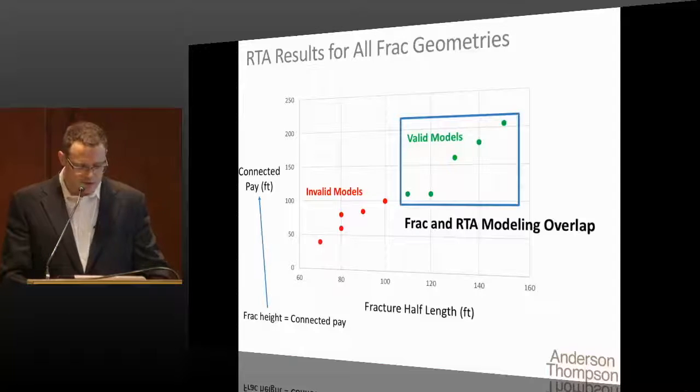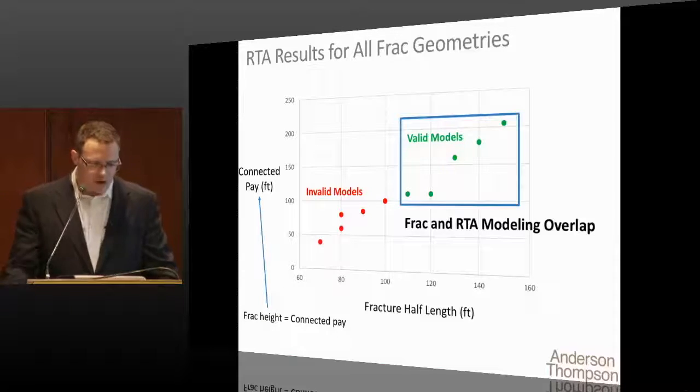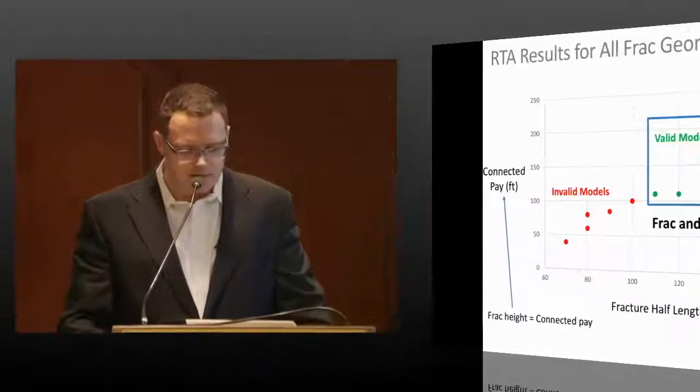Anyway, we're still down to these 5 runs. How do we hone in on our description further? Well, should frac modeling results, meaning XF, HF, and KFW, be interpreted at the end of frac treatment? This is what I was alluding to at the opening of the case study. Can we learn something from running these frac models a little bit longer?